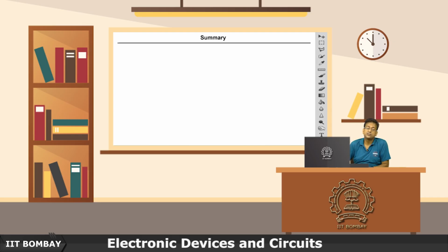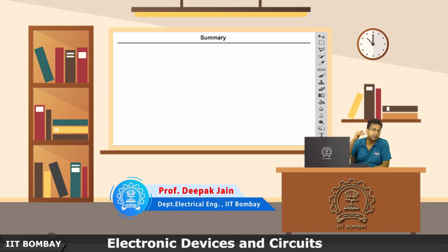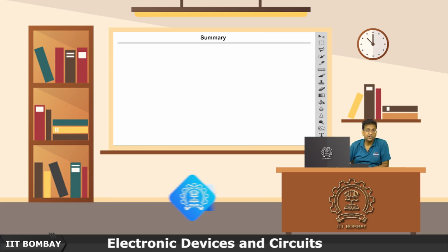Then we discussed the case of the quasi-equilibrium state, where there are some external forces, electron current, voltage being applied, or exposure to light. So in that case, you can say we have two Fermi energy functions, two Fermi energy levels, one in the conduction band and one in the acceptor level. So always keep in mind what semiconductor is there and what the conditions are. The external conditions define our layout.